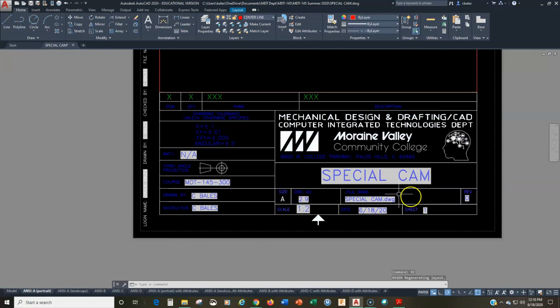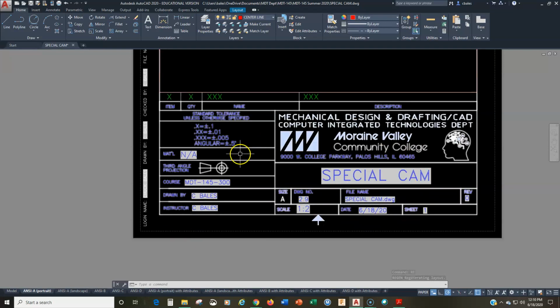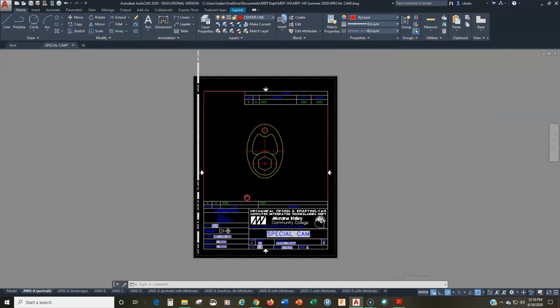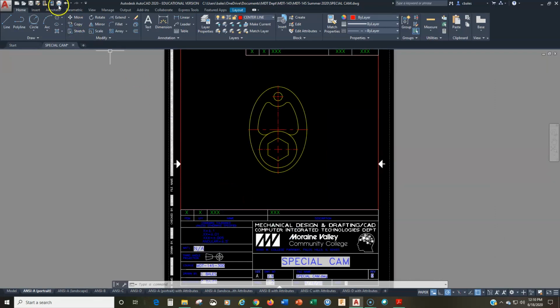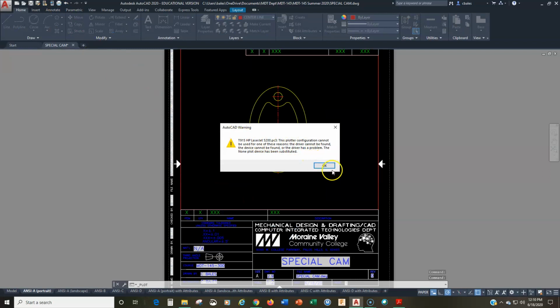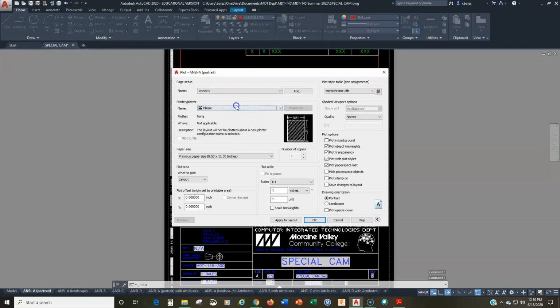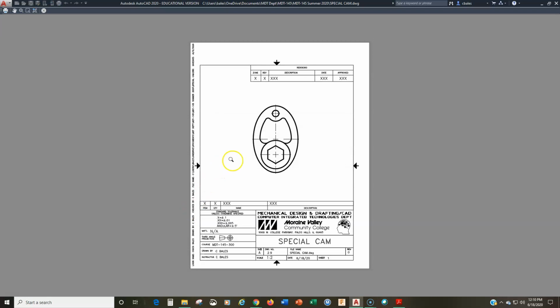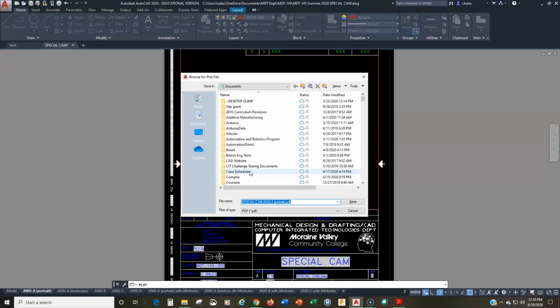All right. Looks all beautiful, everything checks out, and we're ready to prepare it for printing. Okay. So we go to print, we ignore that warning, and we choose our high quality print. Everything's good. Layout, we preview it. Everything looks good still, and then we plot it.